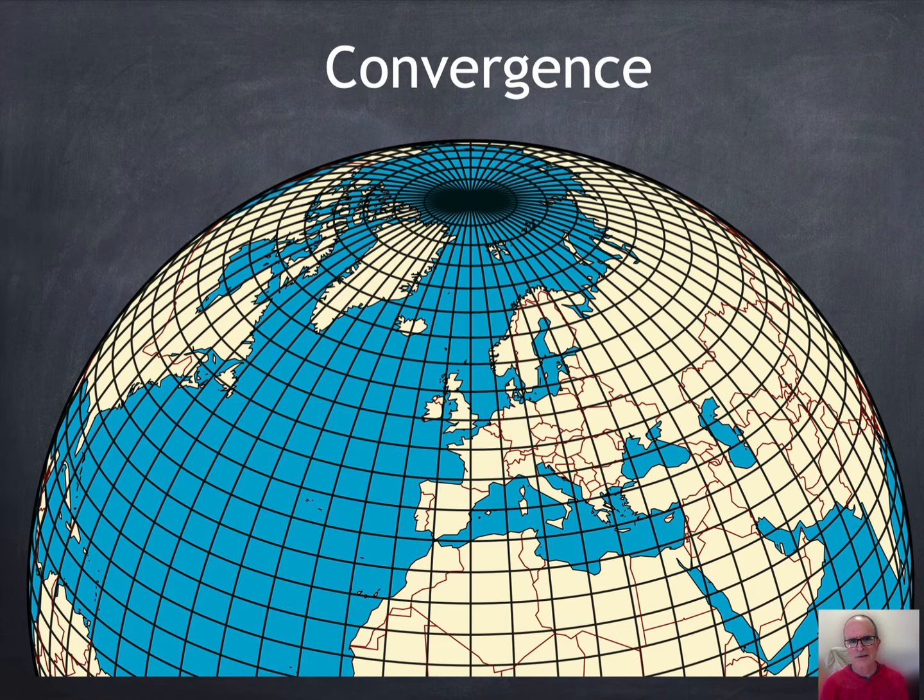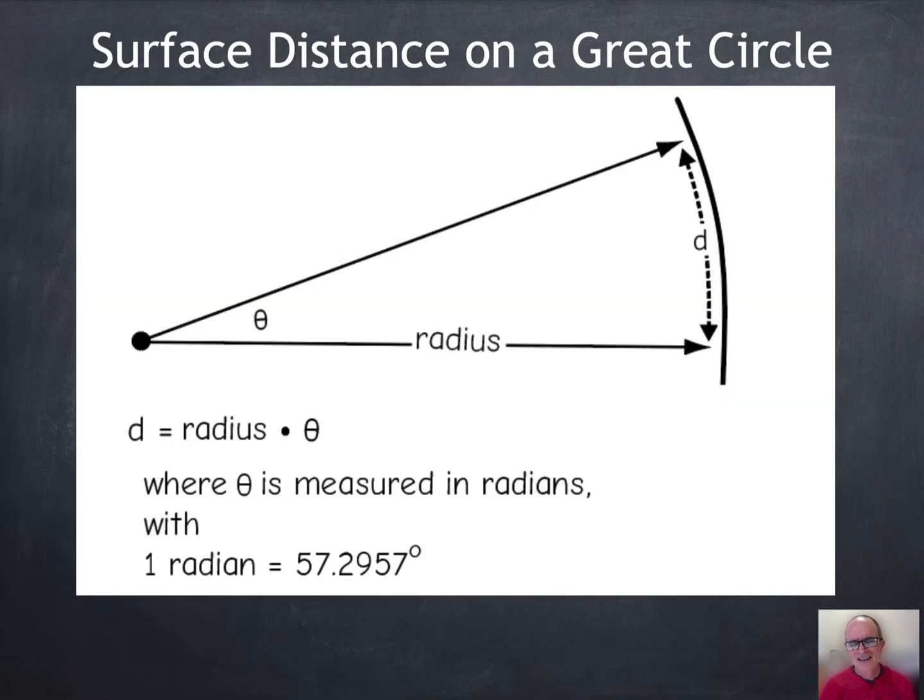They converge. So there's nothing really Cartesian about this because they're not parallel. They intersect. These lines that form our grid, Cartesian, they are at right angles. Now, because we're doing measurements on curved surfaces, a lot of our calculations here involve the radii and turned angles. And distances measured on the surface we calculate often by doing angle measurements and knowing this radius.